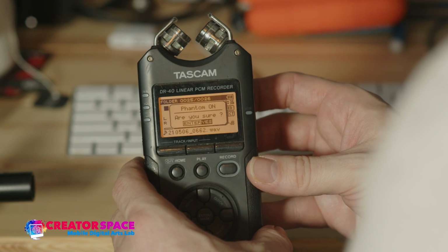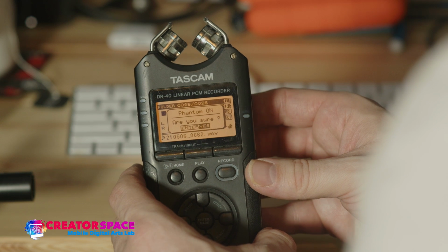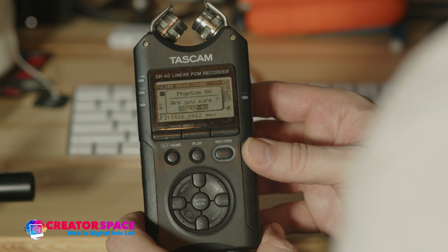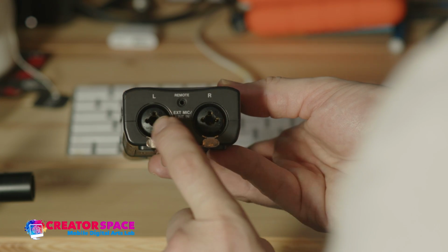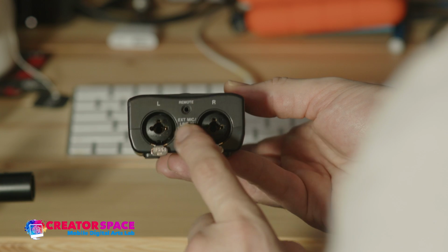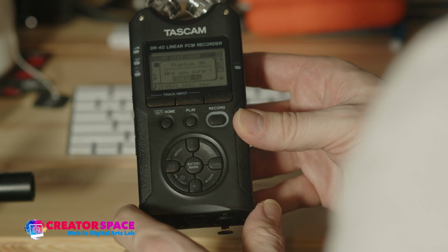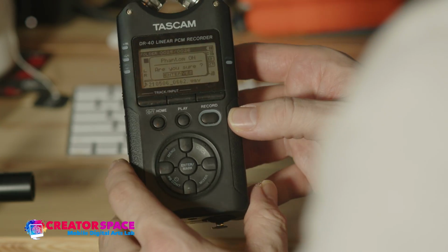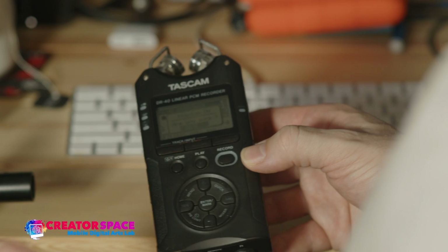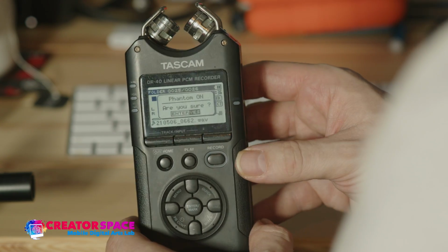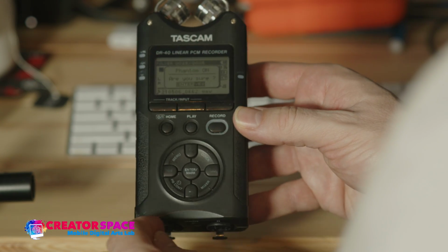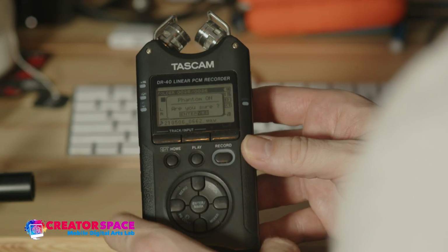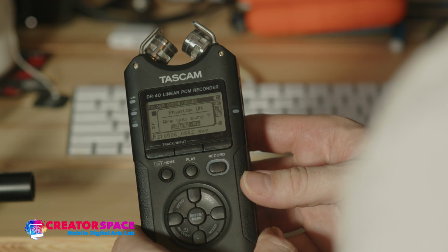And what it says here, it says Phantom on. Are you sure you want the Phantom on? And it gives you a warning. We've default set these up so that channel 1, so you can see here's the XLR quarter inch input, channel 1 will have Phantom power enabled, and it's ready to go that way. The reason being is we've designed these packages to work in a specific way, and it's just something to be aware of. If you put in a microphone that does not require phantom power, you could blow the microphone's diaphragm, you could basically break it.